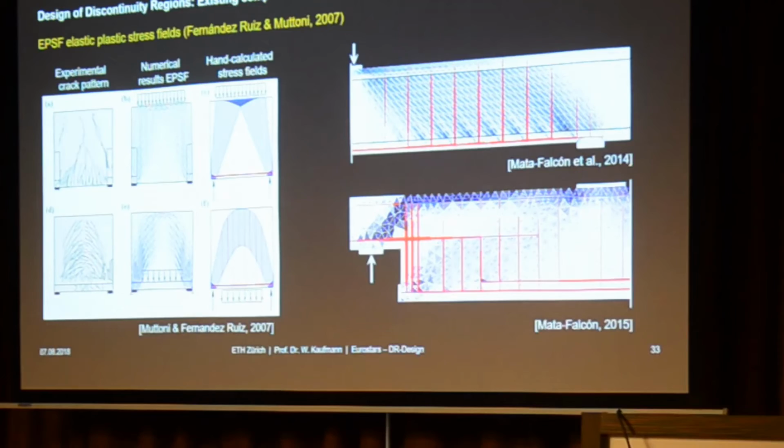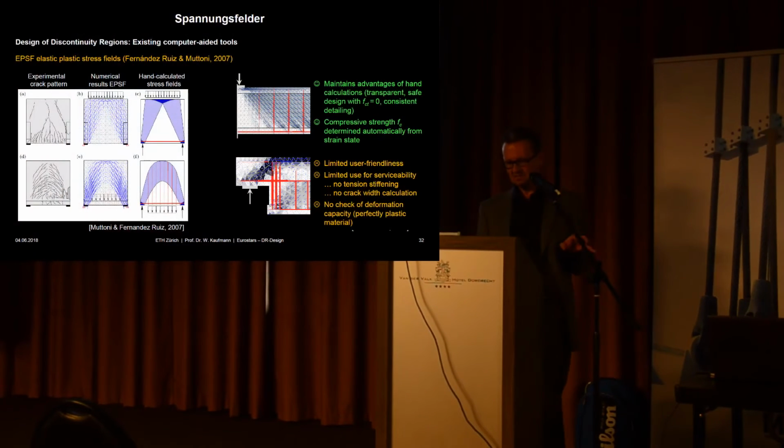Then the thing that's probably closest to what we are doing in IDEA StatiCa is the elastic-plastic stress fields developed at EPFL Lausanne about 10 years ago. I was dazzled when I saw this paper on the left-hand side by Miguel Fernandez and Aurelio Muttoni, colleagues in Lausanne. So you take this example and you apply the load once on the top here, and once you apply it on the bottom. And in the upper case, the program gives you a strut action, and in the lower case, the program gives you an arch action.